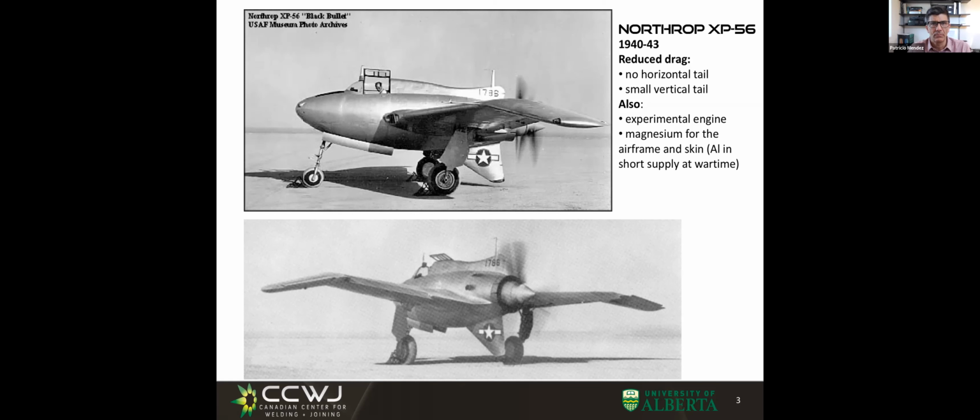And when we talk about the physics of the arc, we're going to see so many interesting things. But among those is that because these materials have a high thermal conductivity and suck up the heat very quickly, they wanted to have a lot of heat put in. And we're going to see that to have more heat in the weld, you can use helium as a shielding gas, and makes it very hot.